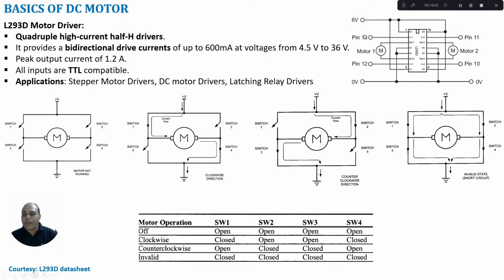Depending upon the signal from the microcontroller, the external supply voltage will be routed to the motors. Thereby the motors will rotate as per the current rating of their nature. So that is how this L293D motor driver works.